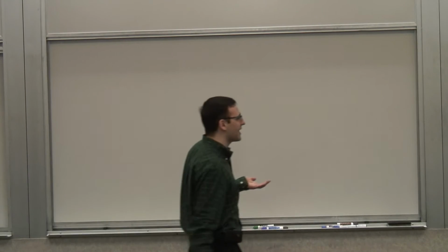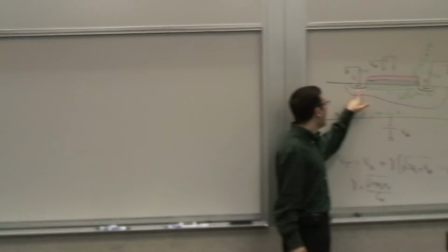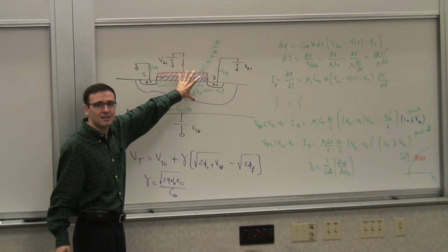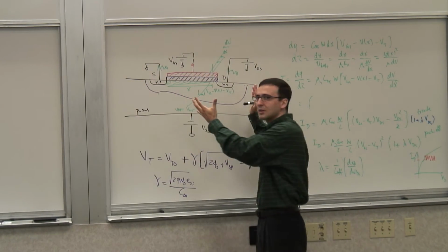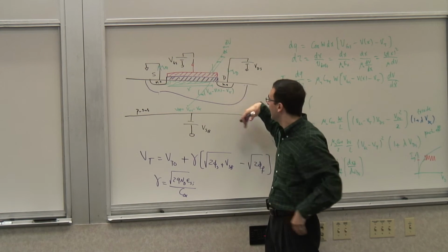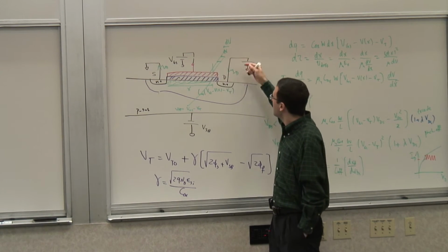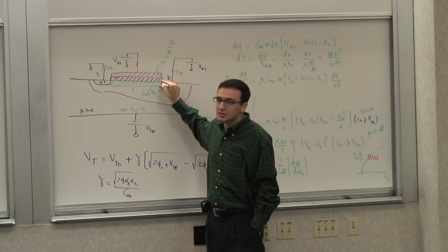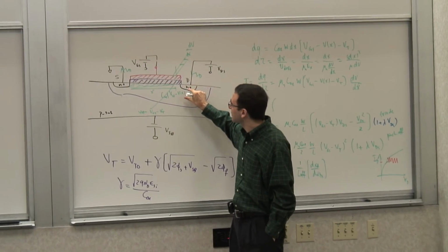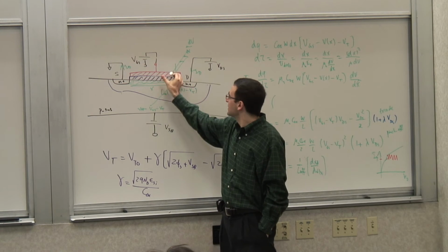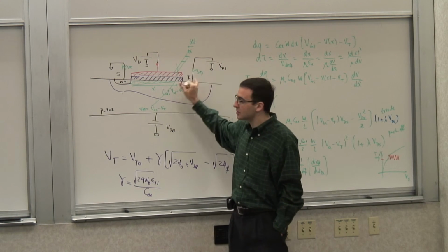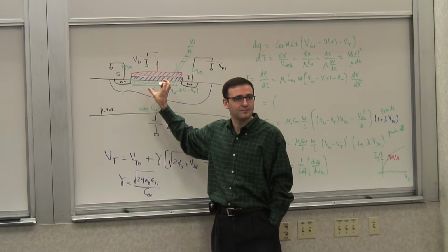Of course, there was a little more to it than that, because if you want to think about scaling in a proper fashion, you have to also scale all the other dimensions at the same time. If you want to do it properly, there's a whole theory of how you can scale a transistor. At least initially, the theory was you want to make all the depletion regions the same, scale them by the same factor, K. Right? So you want to scale the gate thickness, you want to scale the channel length, you want to scale the voltages so the electric fields remain constant.